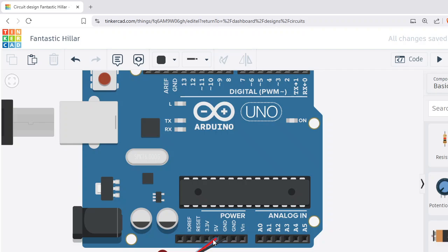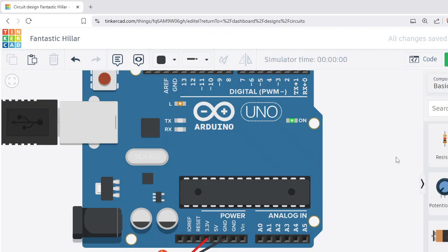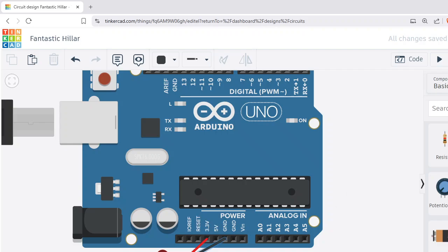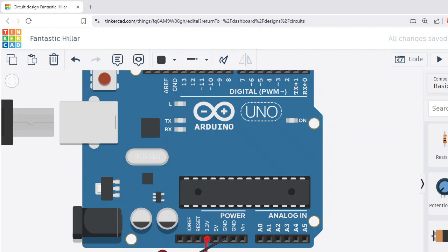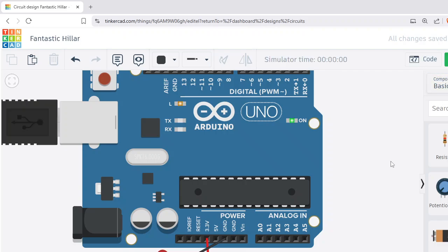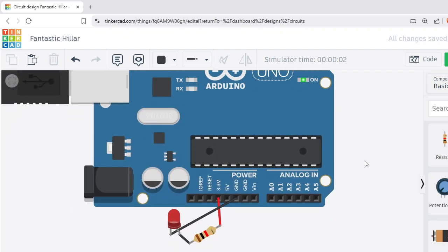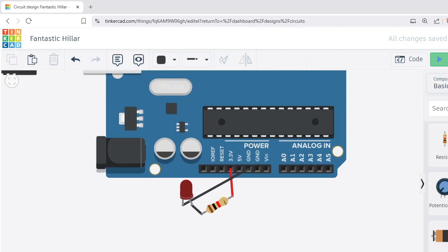All right. Let me give it a smaller voltage. Let me give it 3.3 volts. Should it work? I think it should work. It's still blown. Okay, so what do we need? We basically need a resistor. Let me put a resistor here and connect one part of this to the resistor, the second part to this end. And if I start the simulation, yes, the battery is on. The LED is on. Yes, guys.